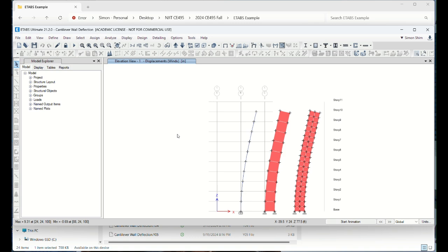You see, it's tilting, not bending. Right? It doesn't capture bending theory, elastic theory, so they don't usually follow bending theory. Somehow internally, it's misreading. This is engineering judgment too. Your knowledge and understanding of finite element software should add this.